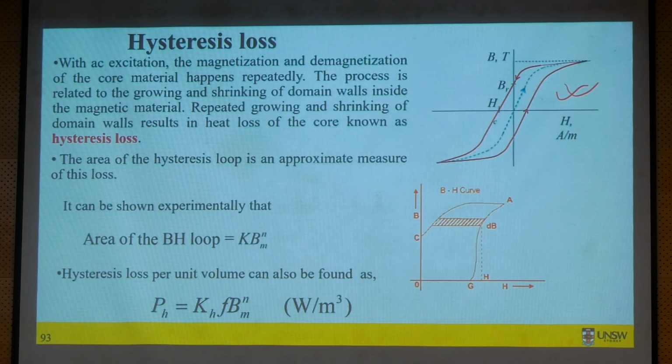It should consume very little power, just only I squared R. But if you try to measure the input power and do I squared R measurement, means measure the current, then measure the resistance, calculate I squared R, input power minus I squared R is not equal to 0. You will have something. So what is that? That is actually the iron loss and your mechanical loss.